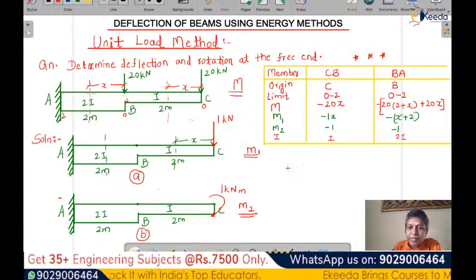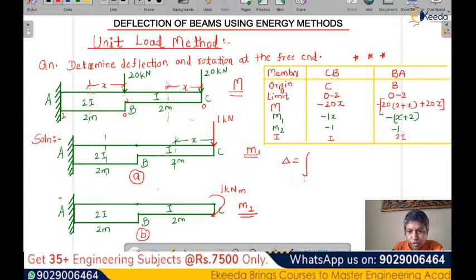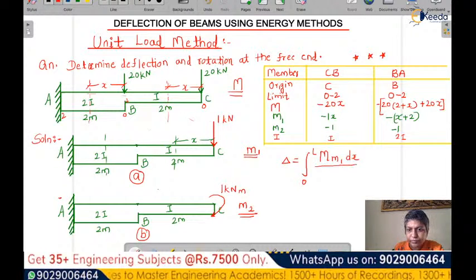So let's write down the equation. What is the equation for deflection? Using the unit load method, we use this formula. You remember, integral from 0 to L of M into m1 dx by EI.